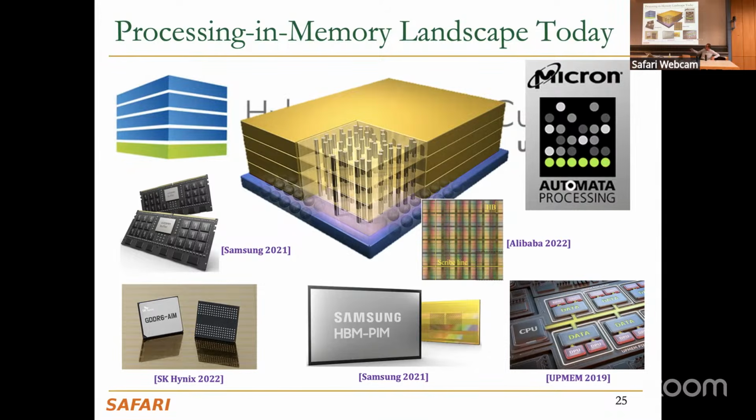And there are also other things that look like this one over here, where you have an FPGA essentially. Next to each FPGA, there are a lot of memory modules, and this FPGA aggregates data from these memory modules and does processing, so that the data doesn't need to go to the CPU or GPU that's far away, right? So this is essentially processing near memory also: processing in an FPGA near memory.